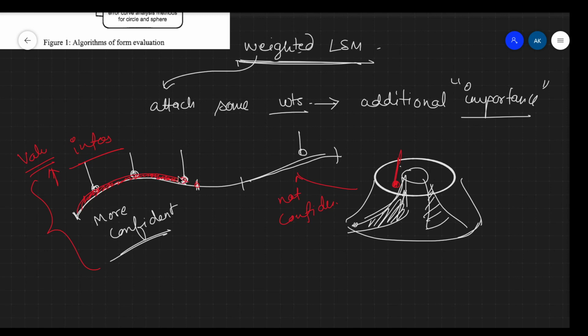So if someone asks what is the importance of the weighted least square method, it is to mask the unnecessary or non-reliable data. It is a concept of weight associated with the least square method, used to mask out unwanted data or increase the influence of reliable data and decrease that of less reliable data, where least square theory is not changed by using weighting functions.